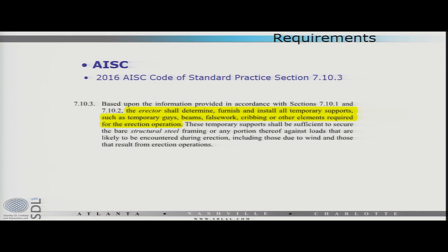There's a lot of guys that have been doing this for a long time, and not every strip mall out there needs a signed and sealed erection engineering plan. Right? But as some of these buildings get more complicated, more difficult, oddball framing, long span trusses, things like that, even metal buildings are quite stability sensitive. It's a good idea to get an erection engineer involved.